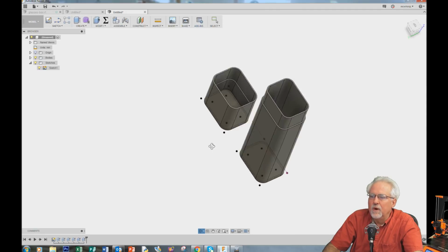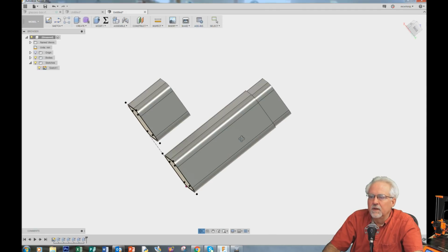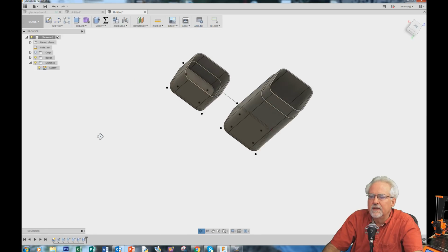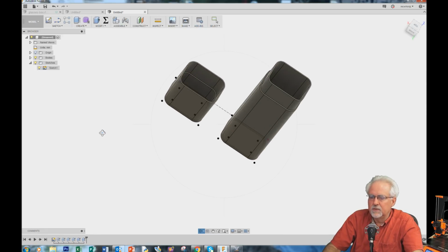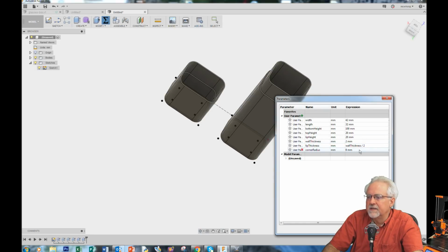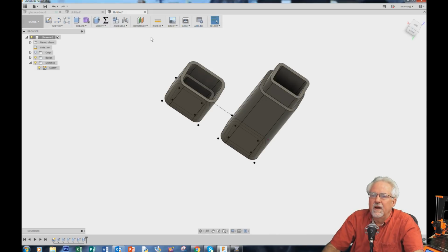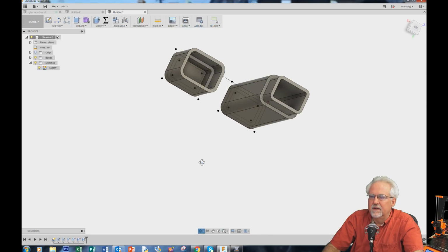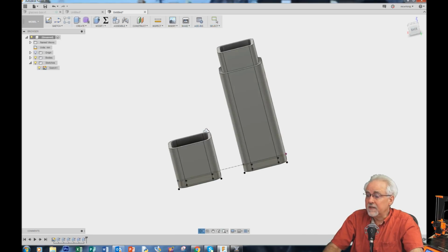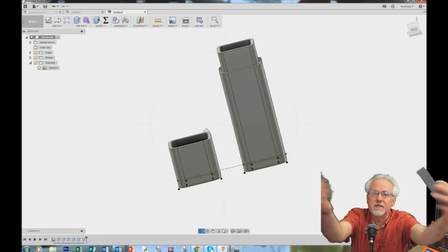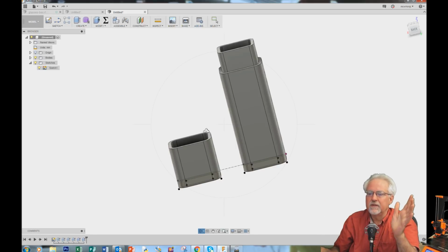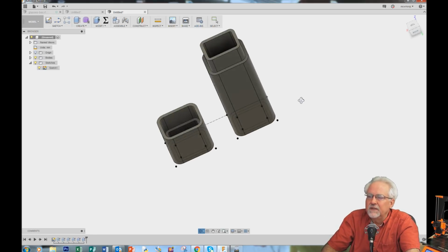All right. What if I got worried that these are a little bit flimsy looking, right? It's kind of flimsy. Is this really going to be strong enough? Well, what I could do is I could come in and say modify and say, let's make the wall thickness 6. Okay. Ooh. All right. How does that look? Well, the good thing is it would fit together. It's still a functioning unit where everything's going to fit together, but it looks a little